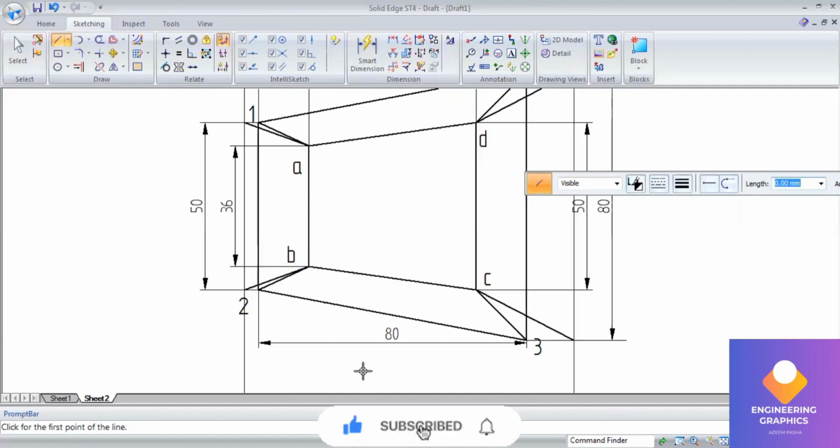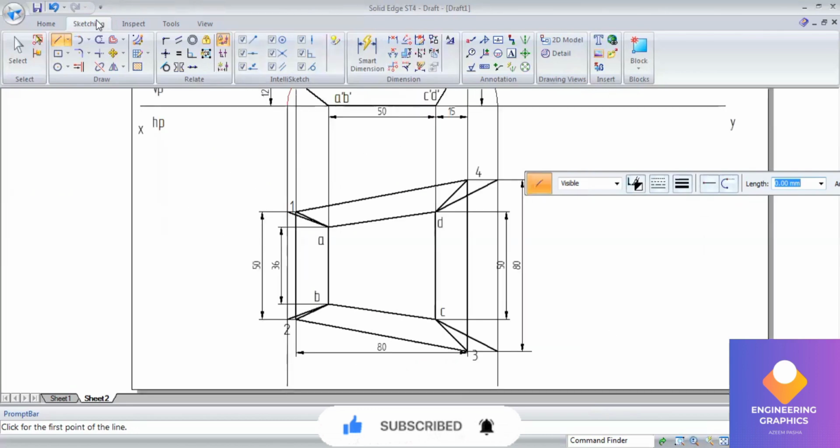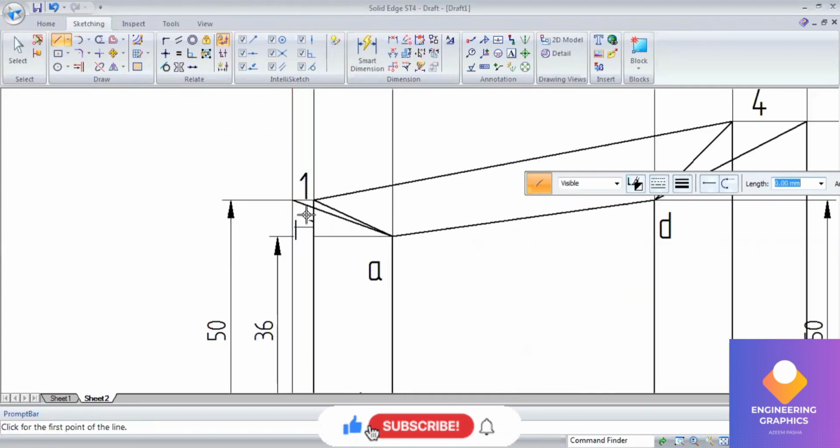Okay, now you join vertical lines from 1 to 2 and 4 to 3. Can project downward this end also. So we have to draw the arc by center. But before that, here you have to connect it with the thick line. This is the development of that particular vertical face.